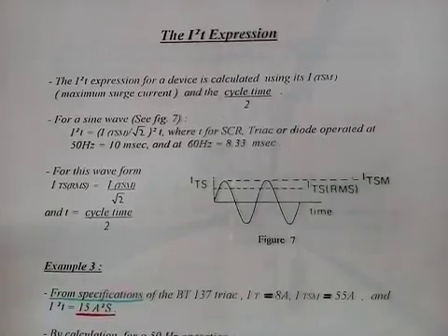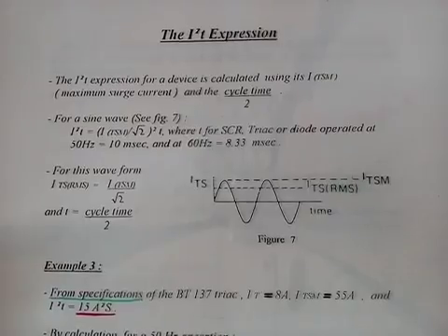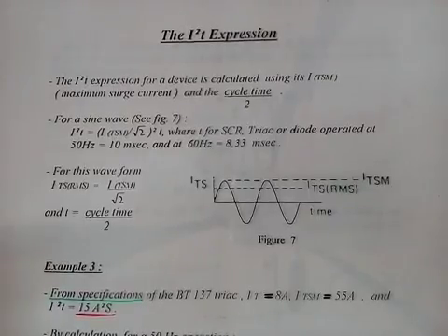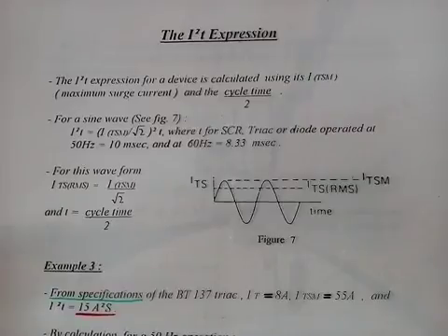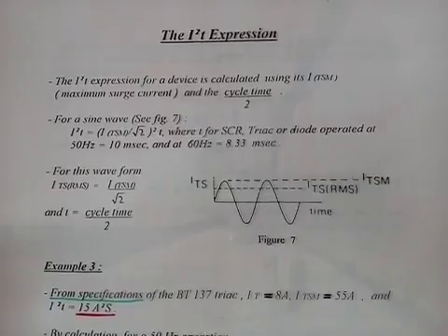It included the fuse types, the fuse thermal storage capacity, the I2t, a few examples, standards for fuses, fuse breaking capacity, and temperature effect on fuses. Okay, my second lecture, this lecture, will concentrate on using the I2t expression to protect semiconductors.